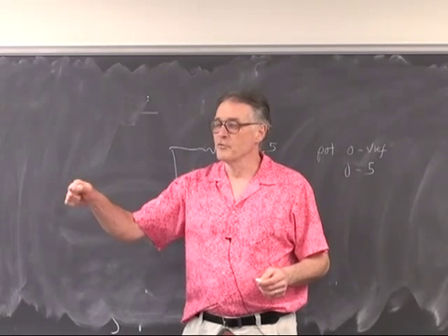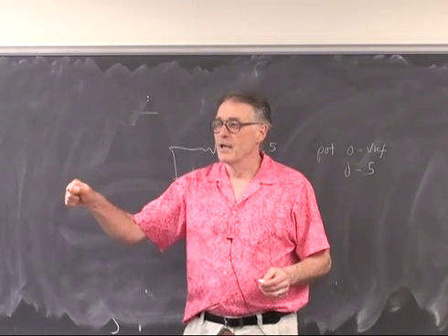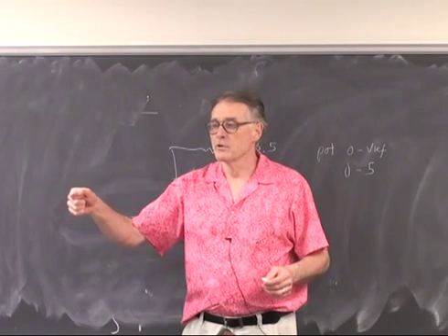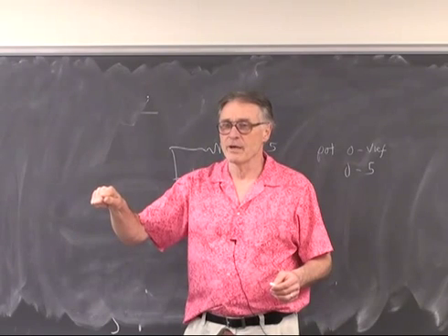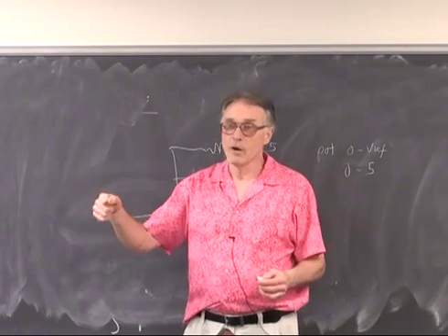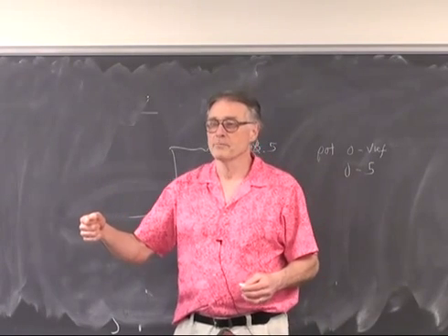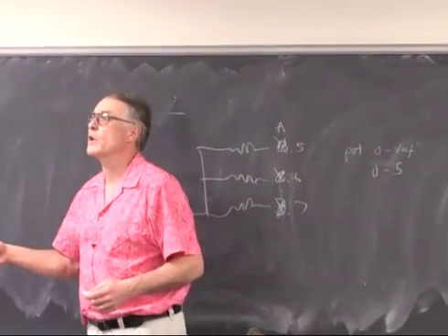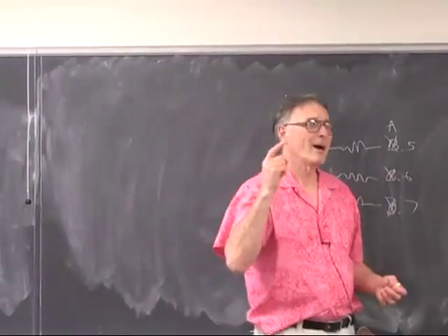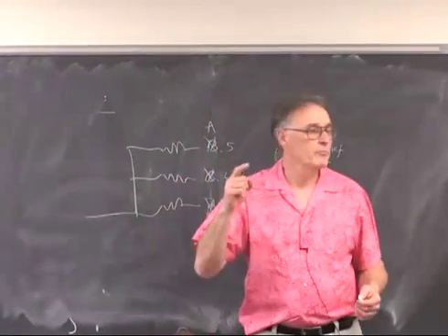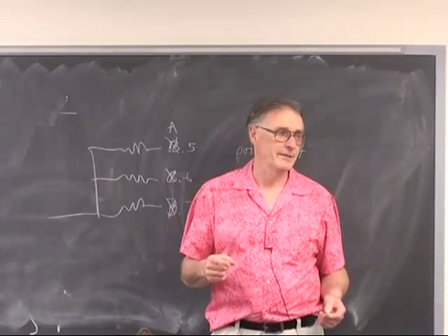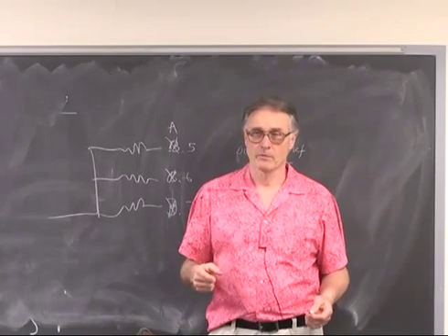All your measurements above 244 hertz will be fine with a times 1 prescaler, and as you go down to 100 hertz, which is the bottom of the range, it'll read 63 kilohertz. Why? Because timer 1 is overflowing. So you have to auto scale by changing the prescaler to divide by 8 for low frequencies.